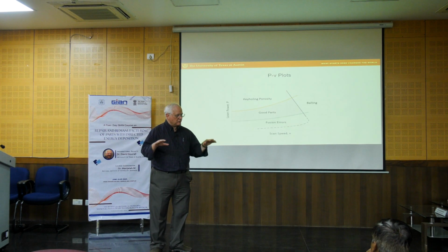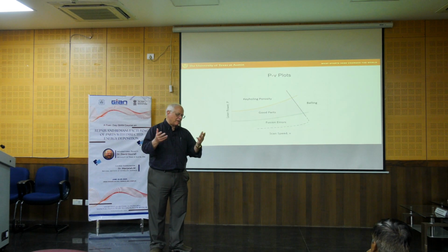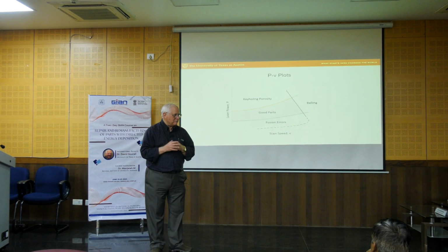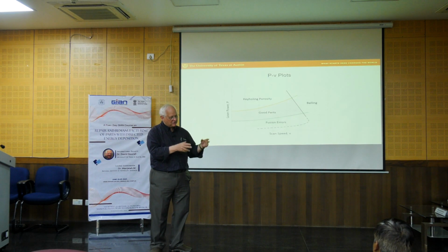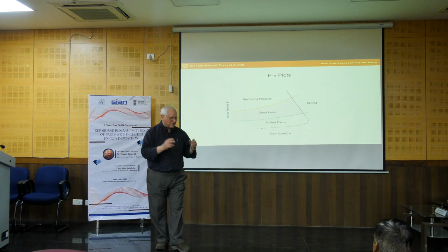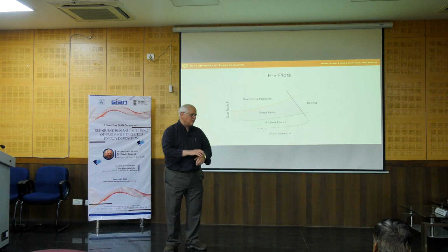Those tend to be the two trade-offs. Clearly, we could argue you move to laser-based DED and can do better part quality in terms of geometry, and with powder bed we can speed up the process by using multiple lasers and other things.